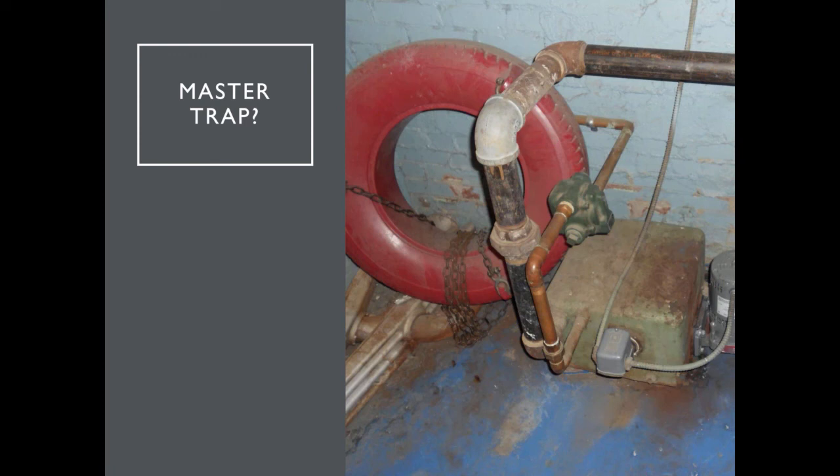They have a combustion air in a can, it's called. It's a little fan with a pressure switch on it, and you connect flex duct from the outside into the boiler room, and you wire it in series with the boiler. So anytime the boiler needs air, you're going to bring in combustion air. I hope that answered the question.